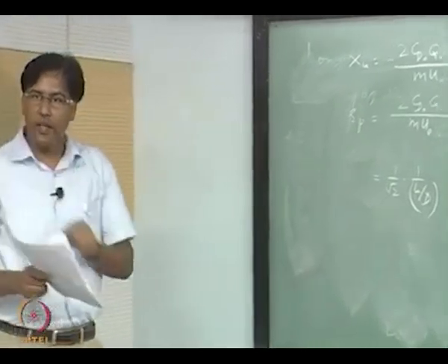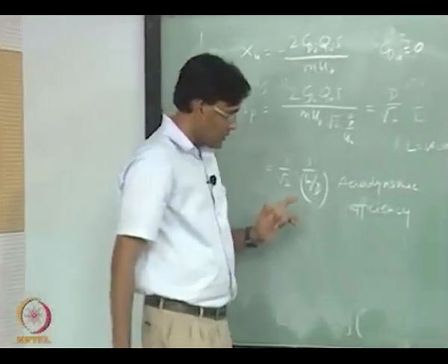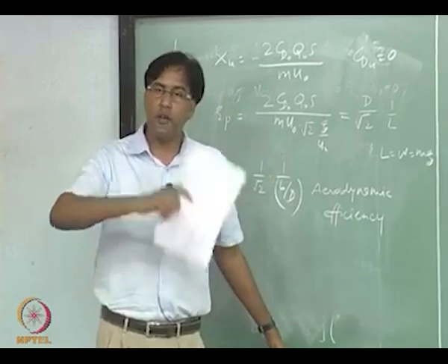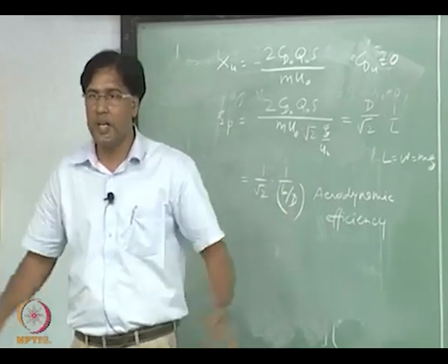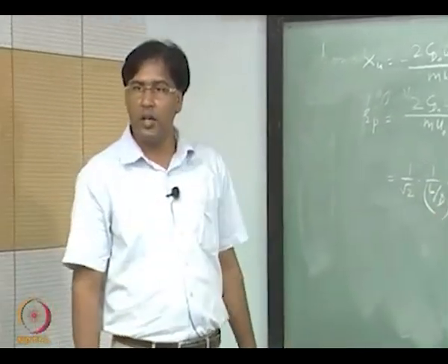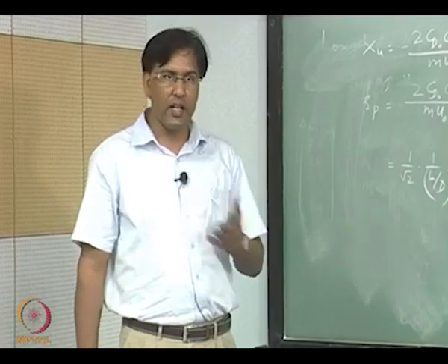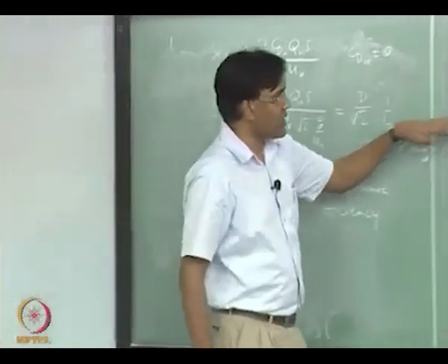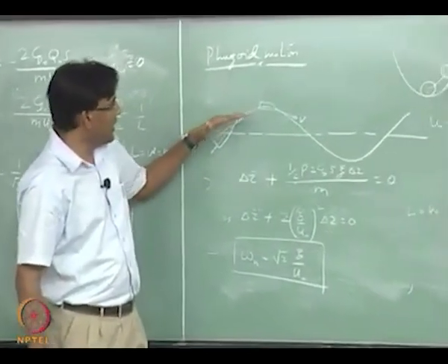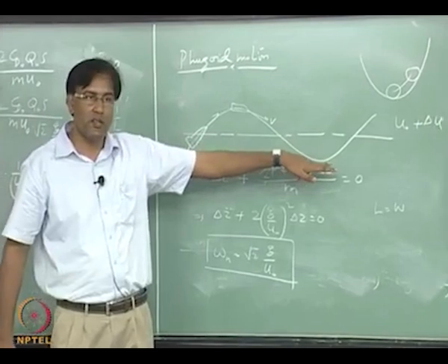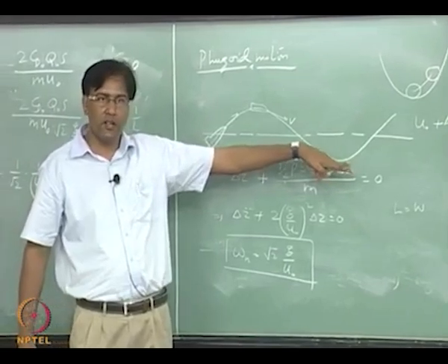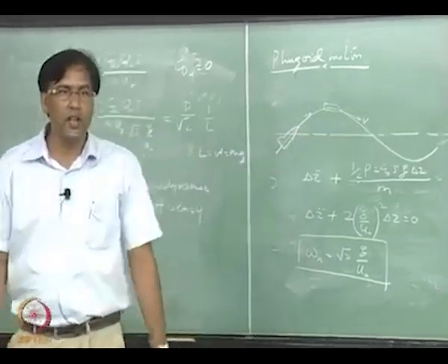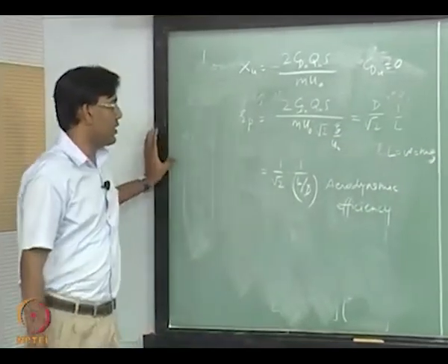right, and Phugoid is a slow motion. You may be able to control it, okay, because the time period involved is large. So, you have enough time to act, but let us say you are very close to the ground, this kind of motion is going to take the aircraft up and then hit the ground, right. If it is very close to the ground, it can give you a bumpy ride, like hitting the wheel on the ground and so on,